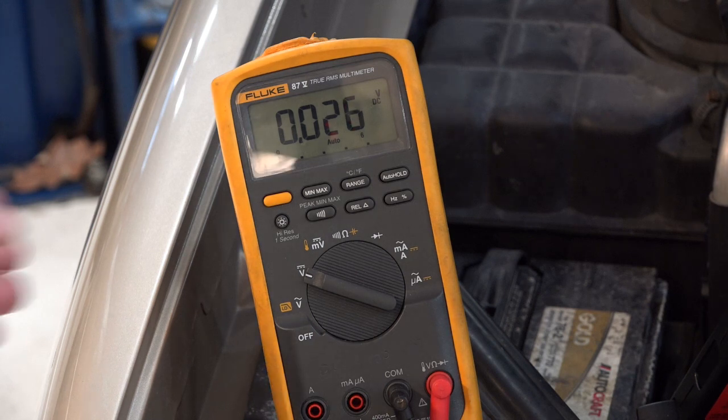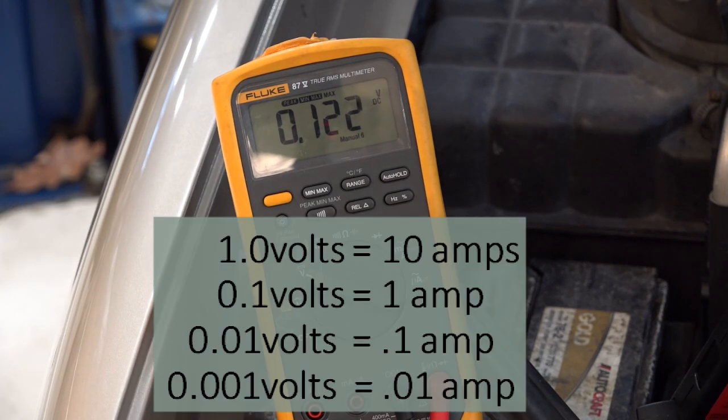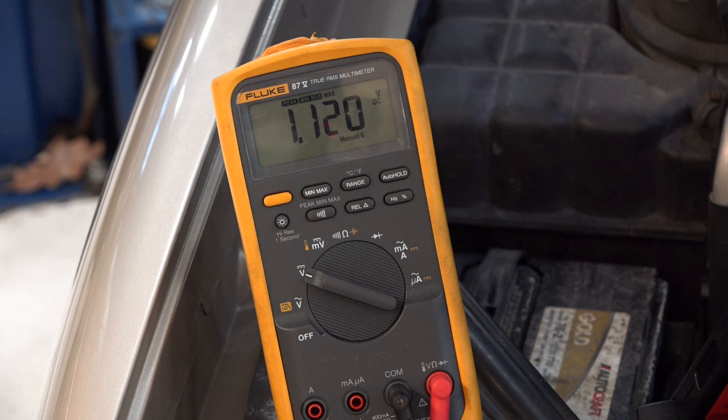So I'll go ahead, min-max, peak min-max. Whoa. Now, as we saw right there, that is 11 amps peak. So this thing has quite a bit of an amperage drain. And again, it's pulsed, it's not continuous. So it's going up and down and up and down. So something is either being commanded up and down, or something itself has just got a mind of its own, is it doing it on its own.